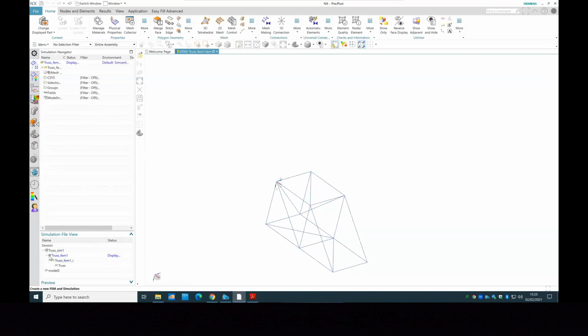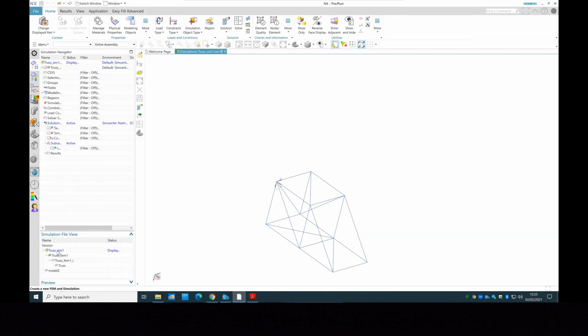Higher level in here, do you see that one? It's a small cubes. That's the mesh. So whatever I'm gonna do with the mesh, in terms of applying the mesh and defining the materials, comes at this level. And you can see once I click on that one, the toolbar on the top becomes different. And if I click on here, that's the actual simulation. Once I click there, you can see that the top will change, sorry, to the simulation level. So the software is smart enough to keep changing the menu for you as well. This is really important because I usually get a lot from the students that I don't get the same sort of toolbar, because they are in the wrong environment.